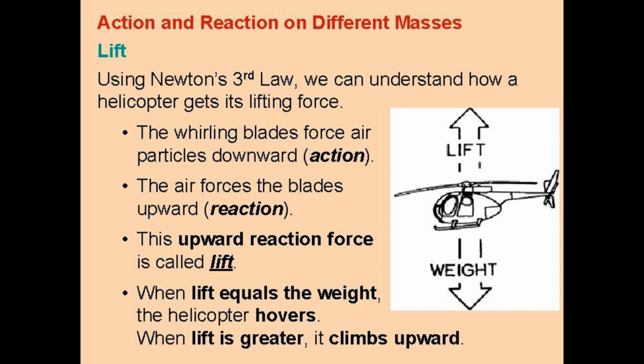Newton's third law of motion. Additional lift is provided by the rotor blade's lower surface as air striking the underside is deflected downward. According to Newton's third law of motion, for every action there is an equal and opposite reaction. The air that is deflected downward also produces an upward, lifting, reaction.